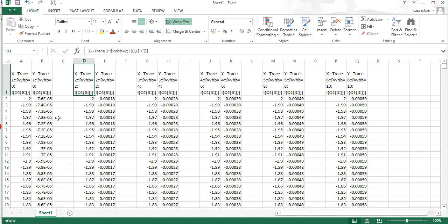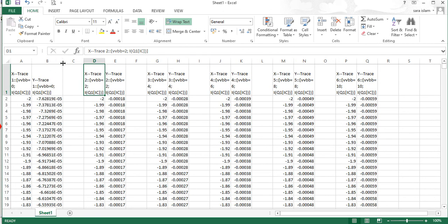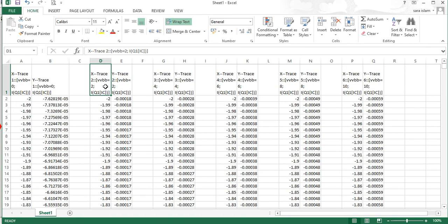Okay, make this version, and then this is your x-axis which was VCC, okay, and this is your y-axis which is your current in milliamperes, right, okay. And similarly these are your x values and your current for your VBB equal to 2. Okay, calculate the collector current, right? If VBB equals 2, you have to calculate the collector current for all the scenarios: VBB equal to 4, 6, 8, 10, that's the VBB. What's the I base current, okay, that should be in microamperes or milliamperes, for which you are plotting this curved line, okay, that's the only thing which is not mentioned here. So you are going to calculate it and write it in your graph,